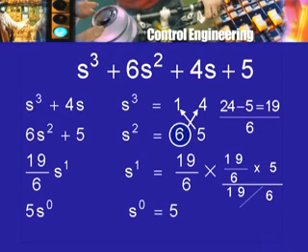So, I will go one step further, s to the 0, and how many coefficients will it have? Only one coefficient, because the polynomial of degree 0 is just one constant. So, I have to find out this number here. Same rule now, but now instead of the first two rows, I am to look at the last two rows that I have obtained, this one and this one. Now, what is my pivot element? It is not 6 anymore, it is this. This is my pivot element.